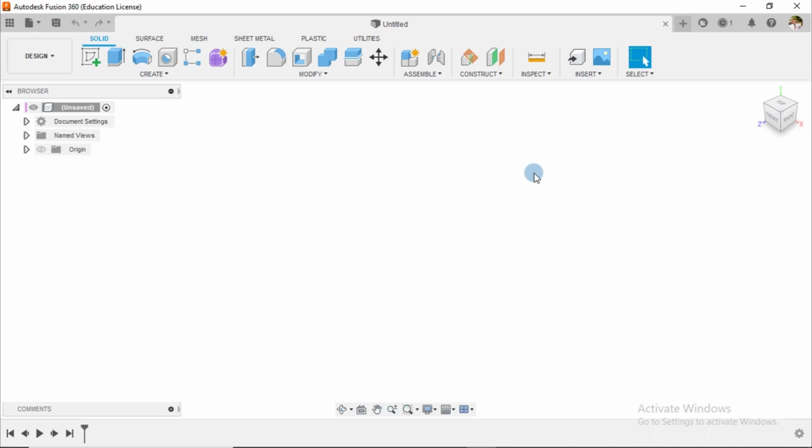Alright, so I'm guessing that you probably already have the exercise with you. For us to proceed, you notice that you have a sectional view at the bottom of the drawing page. So our first assignment is going to be to try to create the sectional view. And since the object seems to be a circular one, what we need to do is to use the revolve feature. So let's just jump right in.